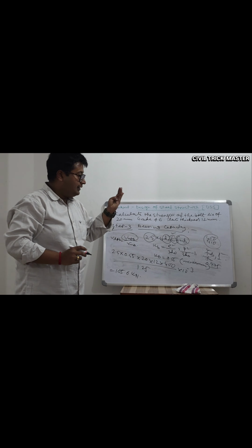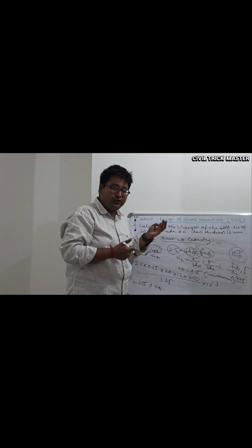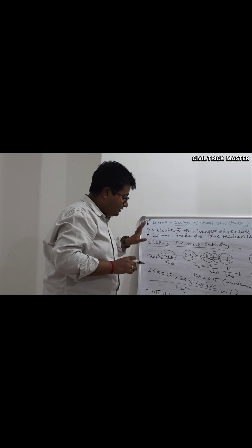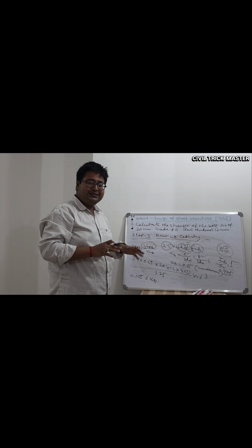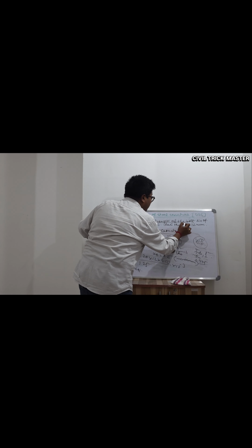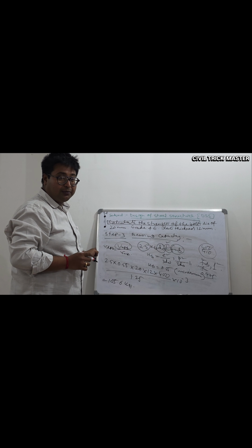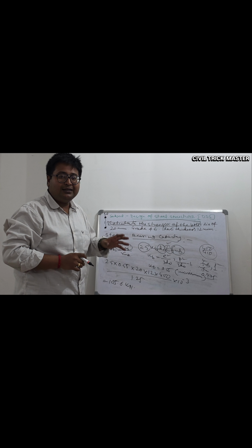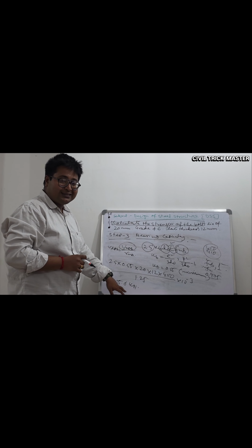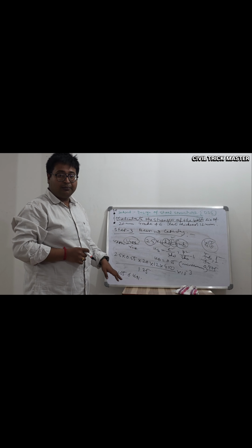So step 1 is the given data, step 2 is our shear capacity, and step 3 is our bearing capacity, calculated, done. So sir, this much is the problem? Yes, that much is completed. What will be the answer? Calculate the strength of the bolt. How could we finalize the strength of the bolt? Here the maximum students make a mistake. They say the calculated value is 105.6 kilonewton, that much is the maximum, so this much is the strength of the bolt.